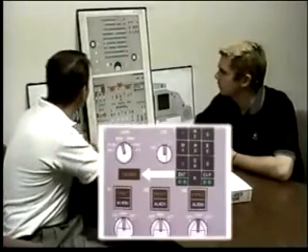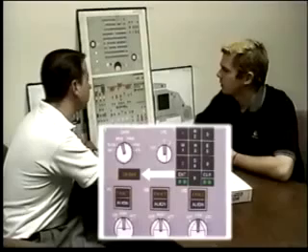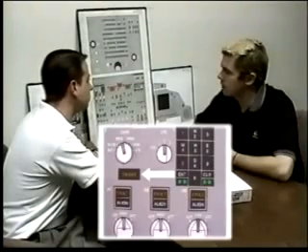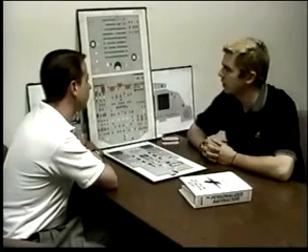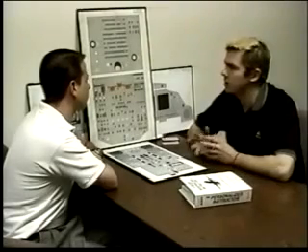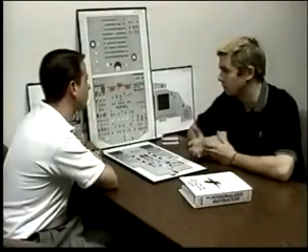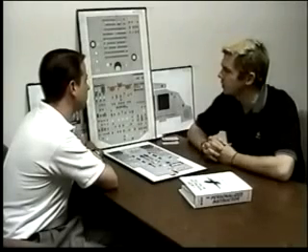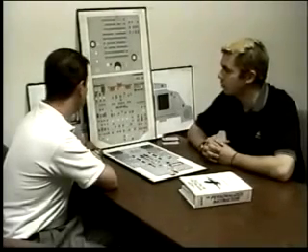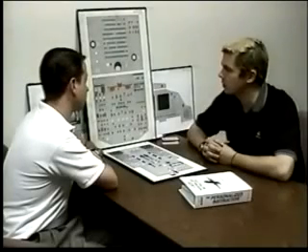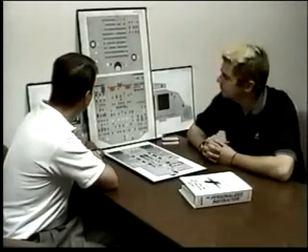On bat light, what are some conditions in which you get an on bat light? Well, the one that we see all the time is anytime we turn them on, because when I turn on 1, 2, or 3, the on-bat light comes on telling me that the alternate source for it, which is the batteries, is picking up the ADIRs. But in flight, if I look up there and I see an on-bat light, that indicates that one or more of the ADIRs are on battery power.